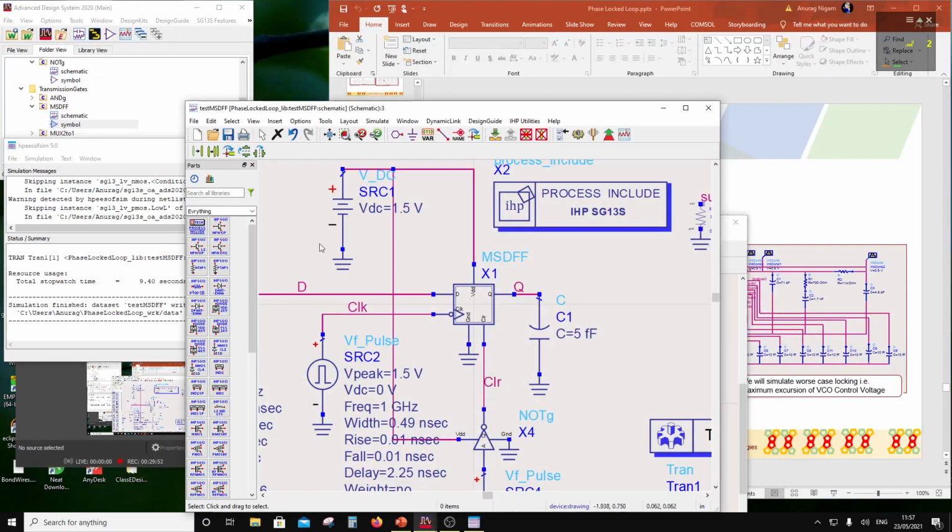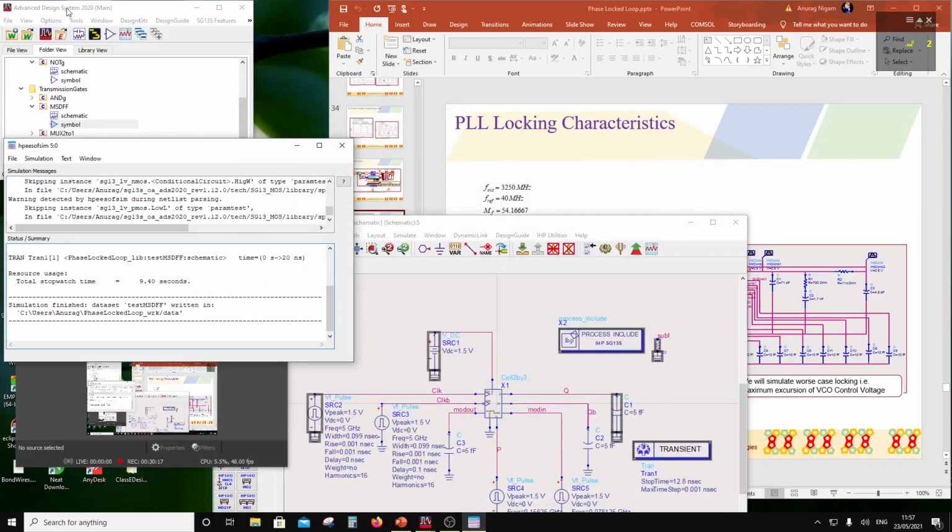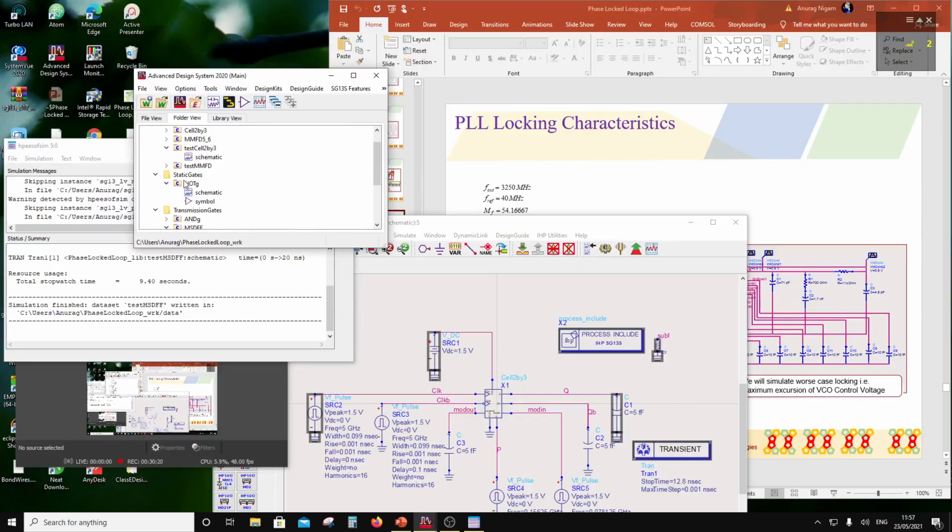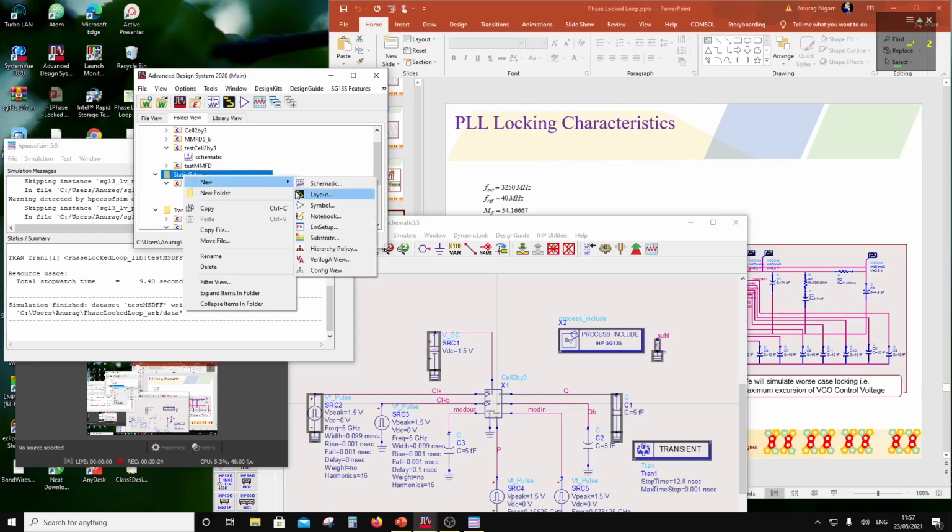Now what I'm going to do is I'm going to do an adder, a full adder. Because in an accumulator I'm going to have a master slave D flip-flop giving a clock delay of 1 clock, and then it is going to add to itself. So that would be the adder, right? So I'm going to implement a full adder. So I need a full adder. I can implement using static gates because this is not going to go up in frequency.